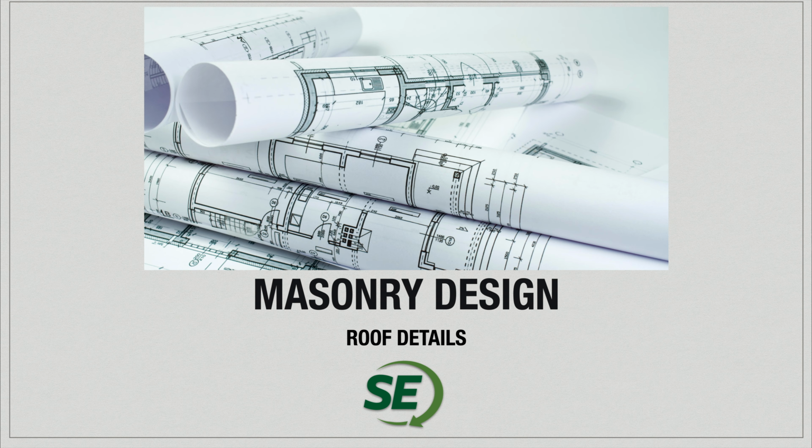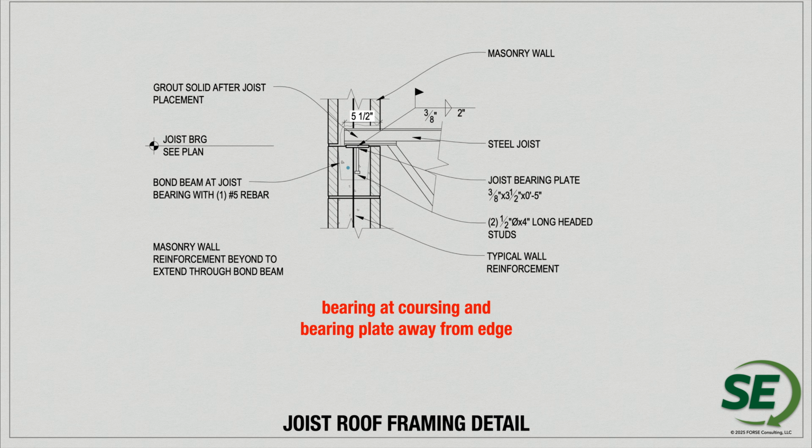Next, we're going to jump quickly to roof details, some of the different comments that we would make on roof details. Looking at joist bearing conditions, it's very common for the SJI manual to point out that we need a 4-inch bearing from a joist to a bearing plate, but that's just not what you need. It's what they recommend. You can get much shorter bearing condition from a joist down to 2.5 inches. So it's just something that you always want to ask for so that we can reduce the size of the bearing plate to just what we need.